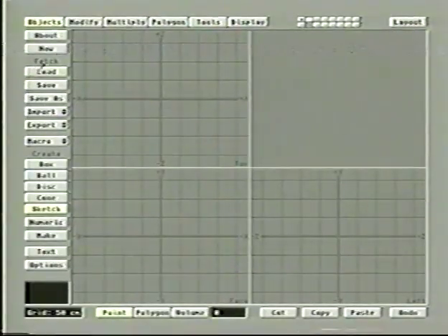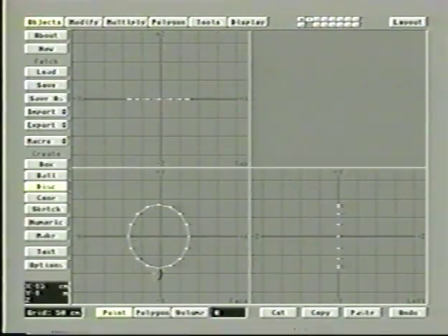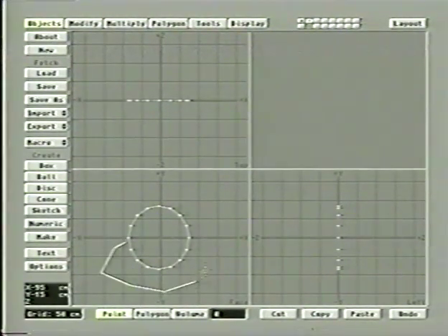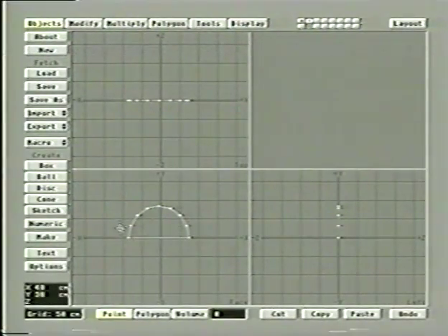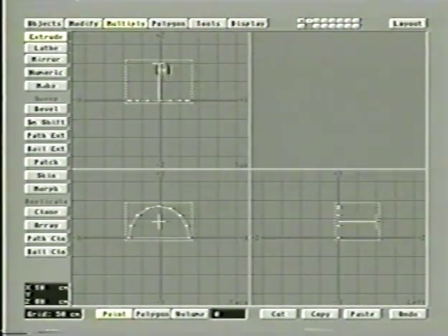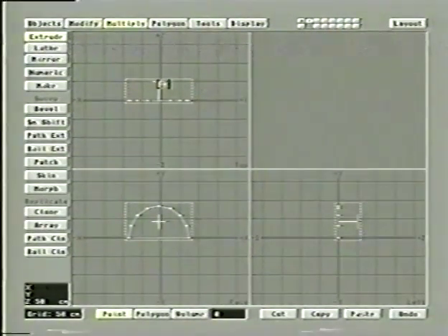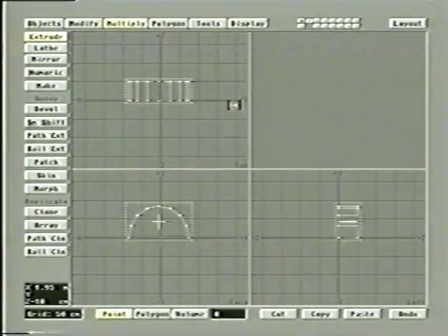And just to do a quick recap, we've already seen it once, but if we take a shape, I'm going to drag out a disk here, and I'm going to make it a sort of semicircle by picking the points on the bottom and cutting them away. So you have a semicircle shape here. What an extrude does, extrude pushes it off into the distance. It takes this 2-dimensional shape and gives it depth, in other words, 3 dimensions, by pushing it off into the background. That's extrude. Now, there's another type of extrusion you can do called rail extrusion, and it works with a path usually best drawn by using sketch mode.